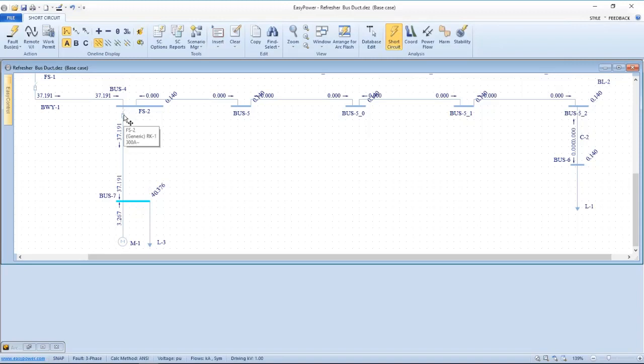So the point I'm trying to make, and this is a decision you need to make as you're doing data collection, as you're looking at the analysis, in terms of the overall contribution to the place where the most hazard exists, which will be at the drop for the bus duct, lumping the loads is a pretty good approximation. But in terms of the downstream protection, like I say, an argument could be made for either summing all in parallel or just sizing this for the worst case, which would be the largest device, which again gives us the largest amount of let-through energy.